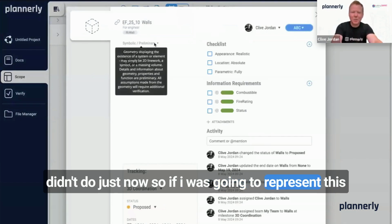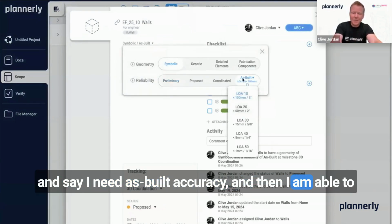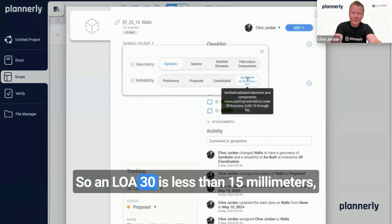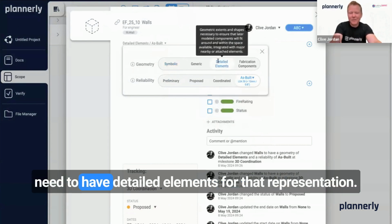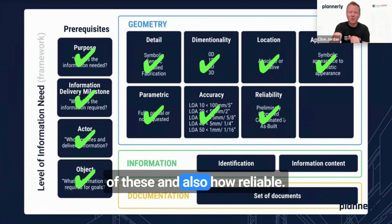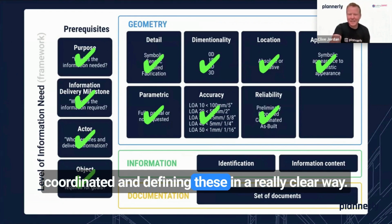So if I was going to represent this and say, I need as-built accuracy, then I am able to pick what that level of accuracy is. So an LOA 30 is less than 15 millimeters, less than 5/8 of an inch, the accuracy. And we need to have detailed elements for that representation. So we start to define more and more of these, and also how reliable. So in our example, whether it's proposed or whether it's coordinated, and defining these in a really clear way.